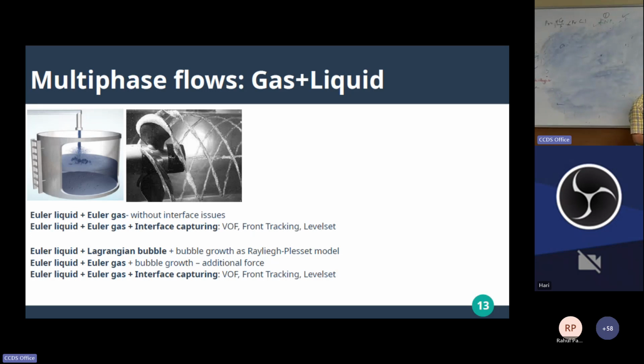Huge expenditure happens just because you make it run fast, and in the local neighborhood some kind of phase change happens in the liquid. Whenever you create very low pressures inside the system by momentum-driven effects, because your propeller is moving very fast, a local suction is created, immediately your salt water starts evaporating and you start seeing tiny bubbles.